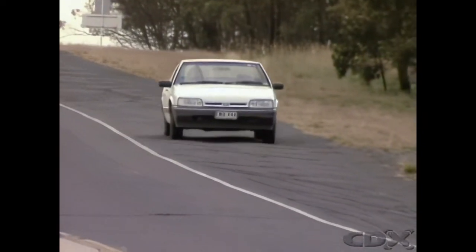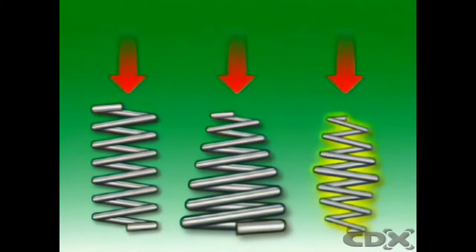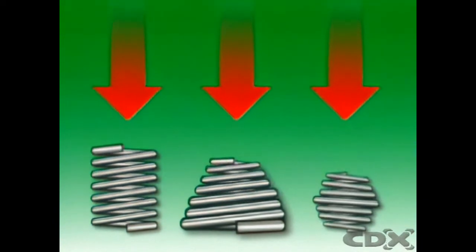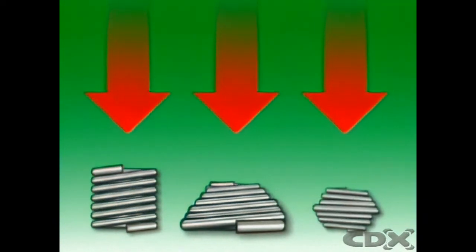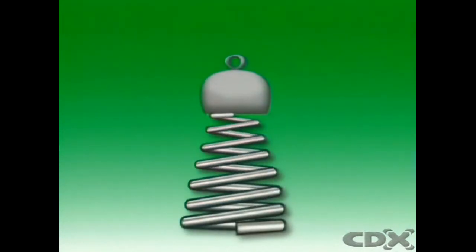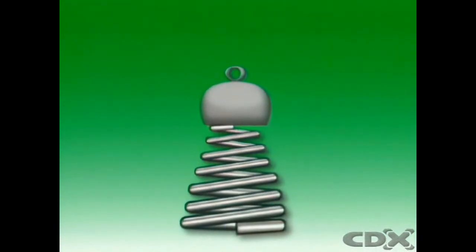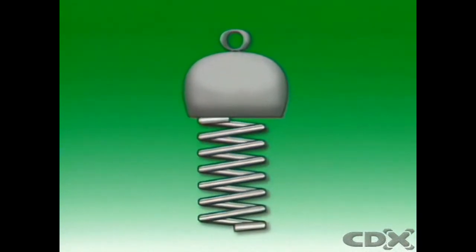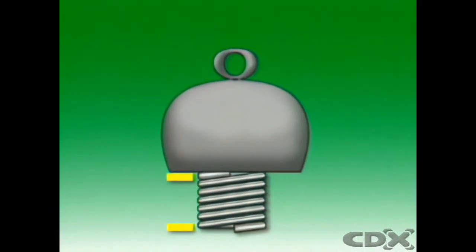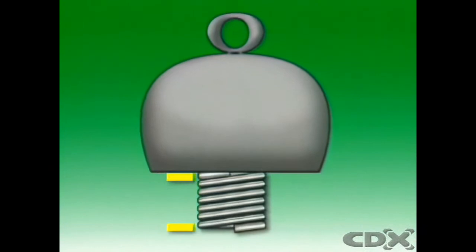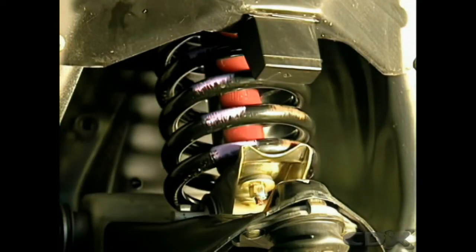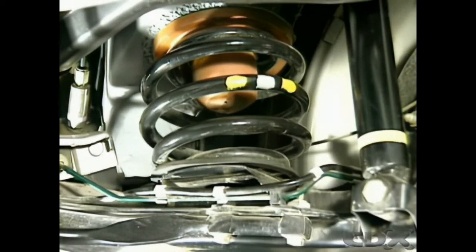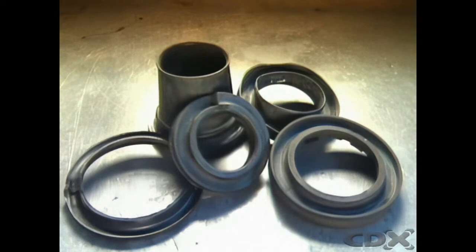As conical and barrel-shaped springs compress, they collapse into themselves. This gives a longer suspension travel for the length of the spring than for a cylindrical spring, which gives a softer ride for light load situations and a harder ride for heavy load situations. As a cylindrical coil compresses, it can become coil-bound, which limits its travel. Coil springs can look alike, but give very different load ratings, which are often color-coded for identification. They normally use rubber pads to prevent transmission of noise and vibration.